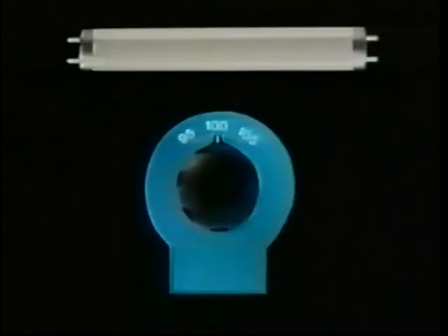Fluorescent lamps are not as sensitive to voltage changes as incandescent lamps. However, increases and decreases in voltage will reduce efficiency and life. Reductions in voltage due to long wire leads or other equipment on the same line can lead to shorter lamp life, early blackening of the ends, and eventual failure of the lamp.